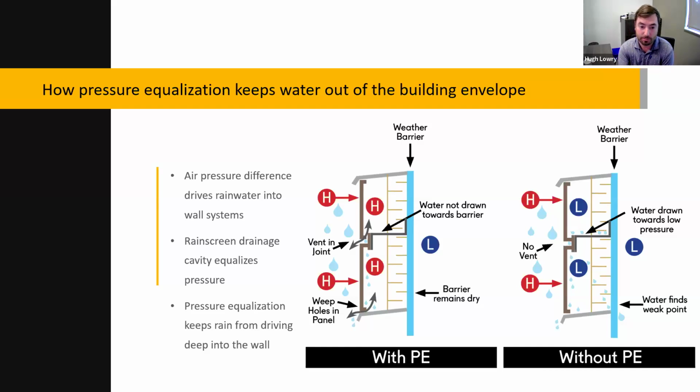If you have some air being let into that cavity, and there's high pressure behind the panel as well, water won't be sucked through that joint at all. So they do that by pressure equalization, by way of compartmentalization and back venting. Any water that finds its way in is reduced, and the residual moisture is returned to the panel's exterior at the drainage plane.